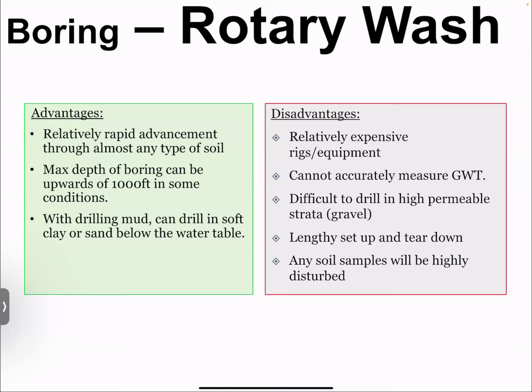This is also really common. Let's say in Florida, you have to go back and retest the soil sample at 200 foot in depth or something. Let's say the client during this phase 2 is like, actually, we want to increase our structural loading. Can we get some more samples from 200 foot in depth? You would use the rotary wash method to get down to that depth and retrieve your soil sample, because it's a much quicker test.